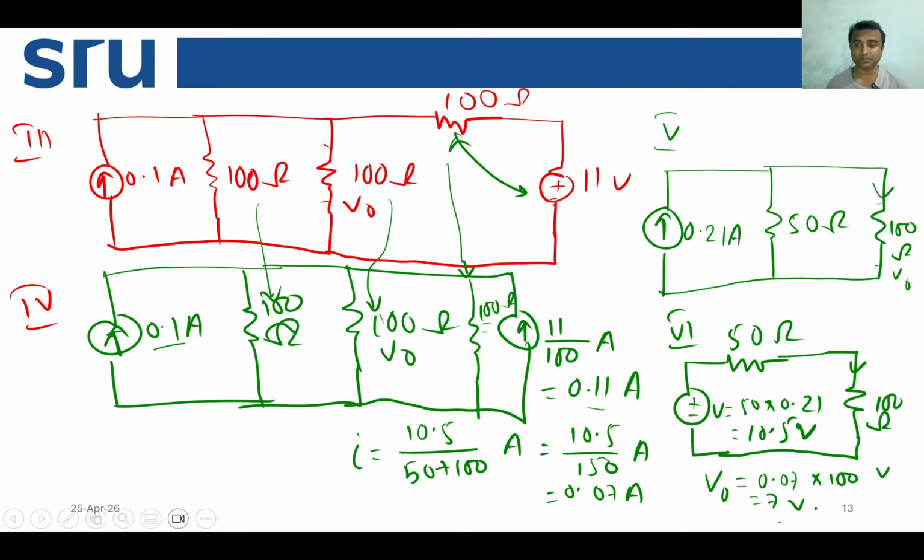So this is pretty simple. We may have gone a bit faster when we came to the third problem, but ultimately the trick is that you can keep on converting voltage sources into current sources connected in parallel, then you can transform each of them from one place to the other, and then it is pretty easy. So that's the whole thing. But you can apply Ohm's law only when you have only one voltage source, and you can have several resistances available.